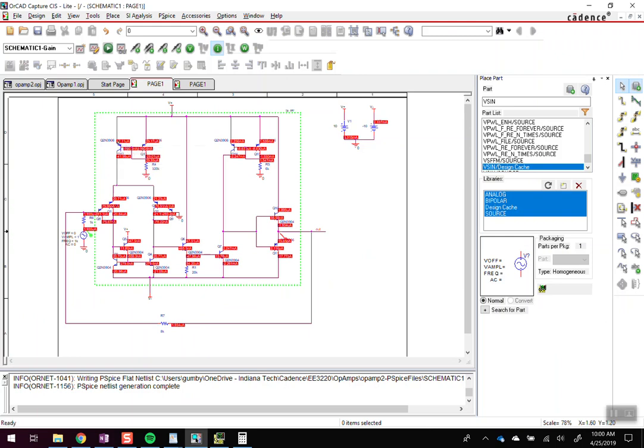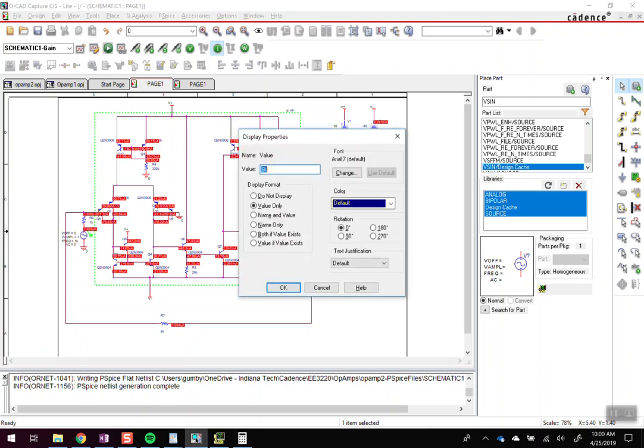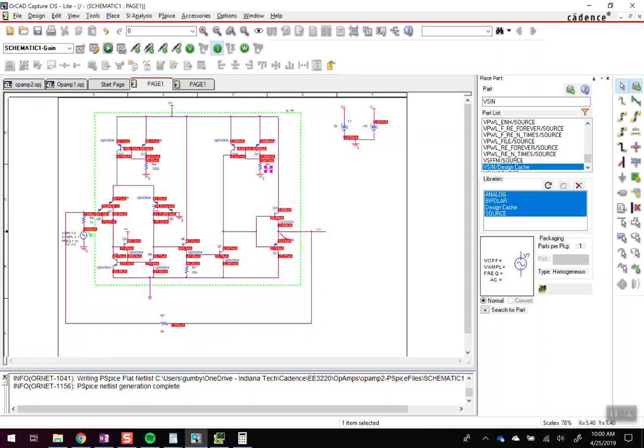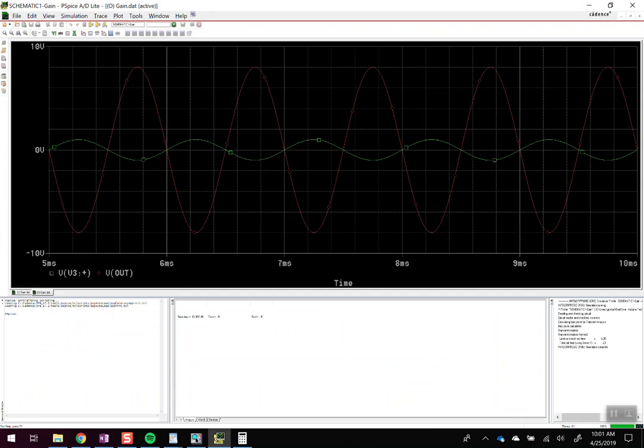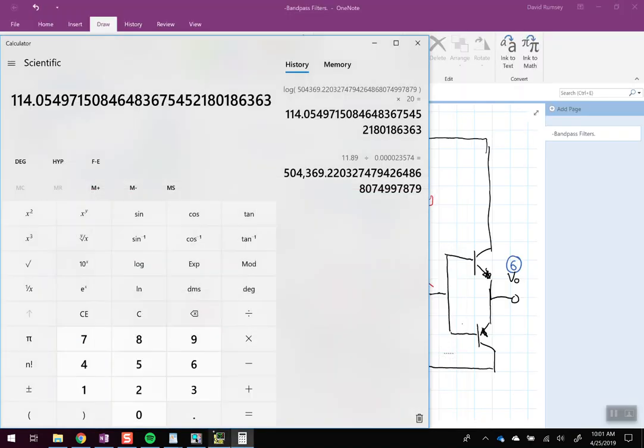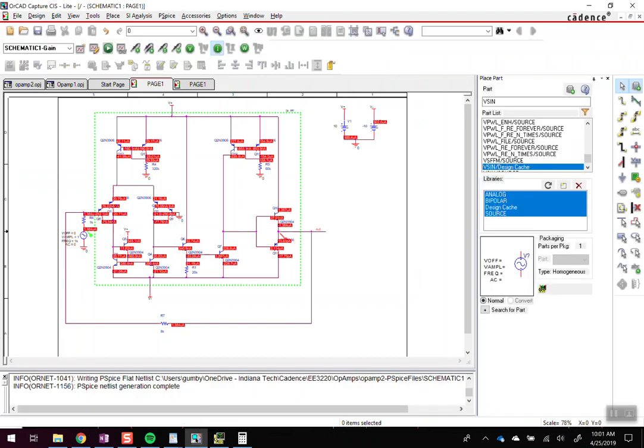In fact, I've got 42 microamps coming down here, and actually I thought I had 200 microamps, but I actually have an error in my design, and it's got 2 milliamps coming down here. I bet if I just changed that to 60, I'd be okay. Let's see what happens. Yeah, now I'm down in the microamp range, but the circuit still works the same. Okay, so let's turn those currents back off.